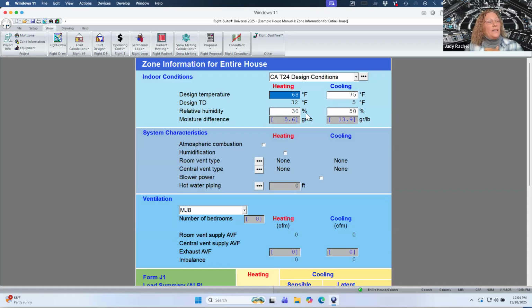The relative humidity is what's really different from the various climates. Pretty much most climates, we want the indoor relative humidity to be at 30%. That's what we can achieve in our homes, and that's comfortable for our respiratory systems. That's part of the comfort zone in terms of the Manual J calculations. In the summer, the indoor relative humidity in a humid climate, it's often difficult for them to get their homes below 55%. And so that's what you design at.